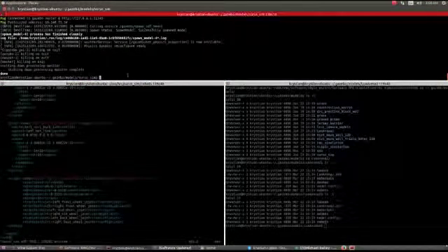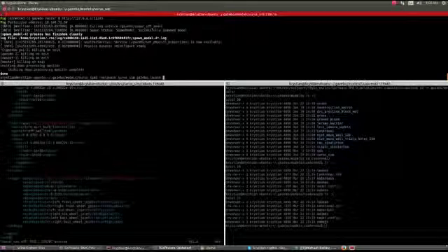So now we can simply exit out of this and rerun the Gazebo simulation. Unfortunately, you can't leave Gazebo open and insert the model anymore, because you cannot run Gazebo standalone and run a ROS plugin without using a ROS launch file and using the Gazebo ROS package and the Gazebo ROS API in order to initialize the plugin. It just won't work.